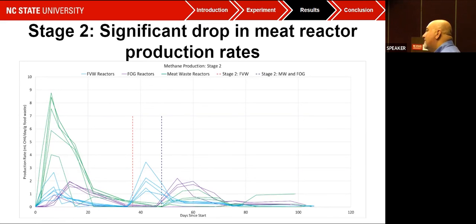I agree with all of those comments. I just wanted to ask something specifically for my own study, for instance the Hezhou study. In some wastewater treatment plants nowadays, there are already applications trying to draw out VFAs. There are acetogenic reactors out there rather than methanogenic digesters. Some of the plants might be facing the issue of methanogenic adaptation and methanogens using up the VFAs.